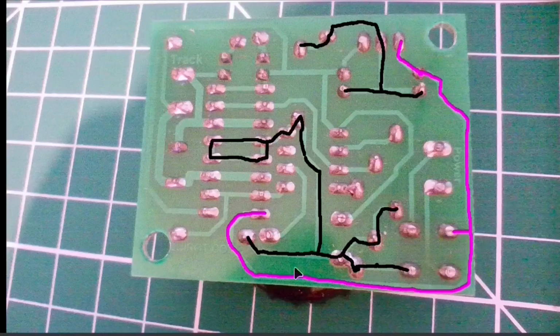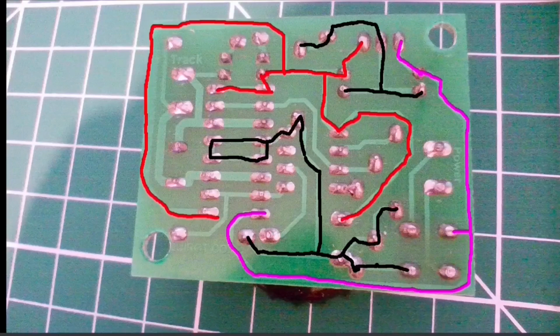Right, so that shows an interesting arrangement here in that driver circuit. It also sort of confirms that this is a voltage regulator. So what's happening is it's taking the 12 volts and ground and producing a lower voltage from it. So let's assume that's 5 volts for now, and let's trace that through.